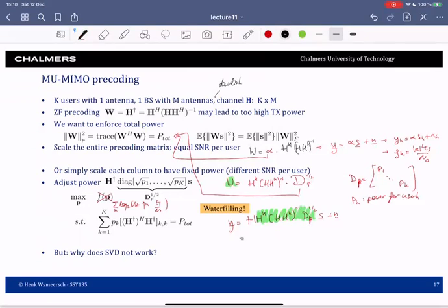And then I can again cancel most parts. So this will give me dp 1/2 S plus N. And then this implies that for user K, it will see Yk, which is square root Pk times Sk plus Nk. And this means that the SNR rho K for user K is Pk times Es over N naught. And then this is exactly what I optimized here in this rate equation. So this is one way to do pre-coding for the case where each user has one antenna.